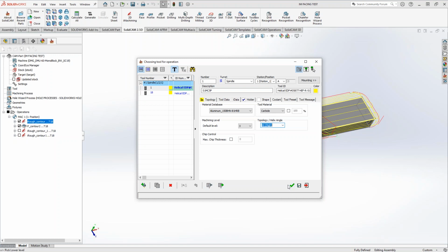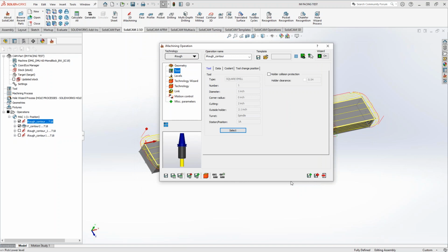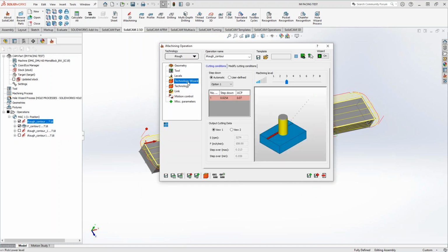Yeah, so the green is going to be your optimal cycle time, optimal tool life, all that stuff. Red will still cut, but it might not get as good a tool life. Same thing with yellow. So what I did is I switched it over to a 60-degree high helix, and let's see if we can get this turned up. So now that brought us up to a 0.7 here. And we really want to be, something one point something or higher is what we're looking for.